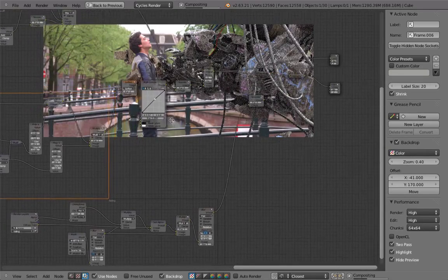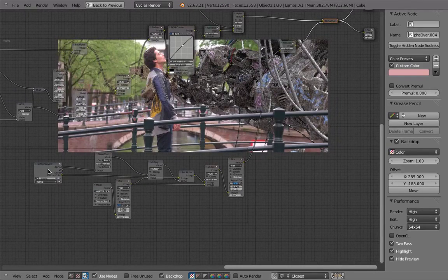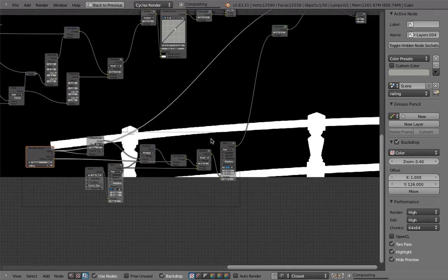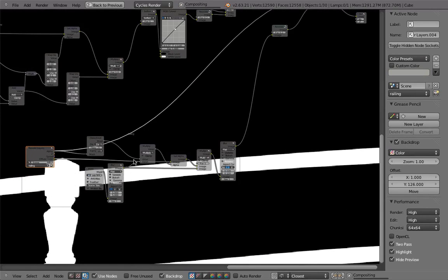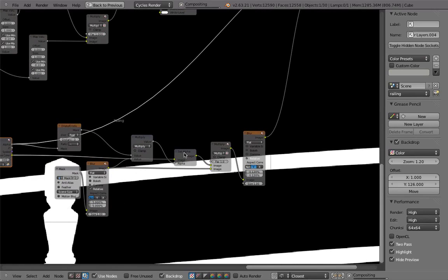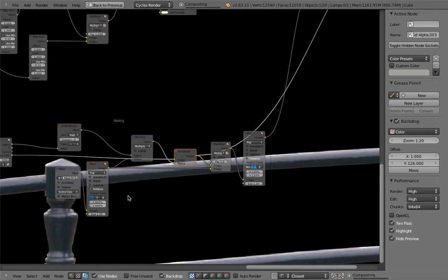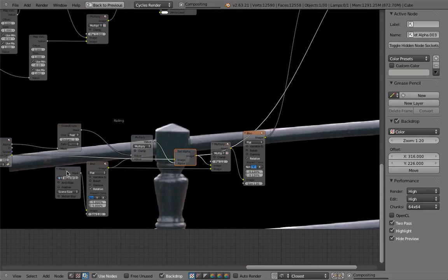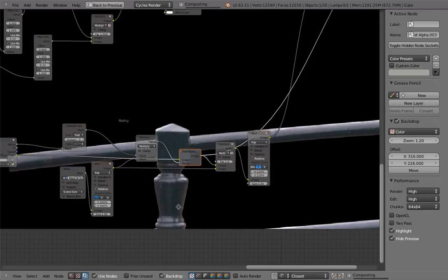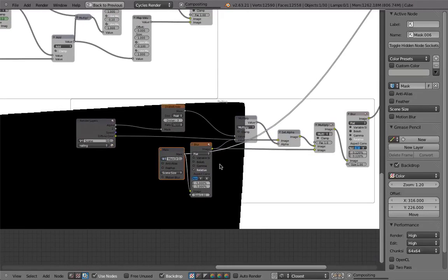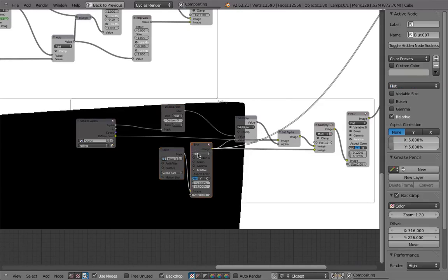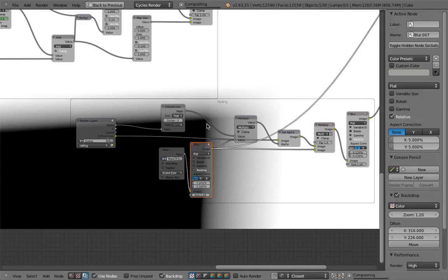Okay, so that's that. Then down here you have the railing. The railing is using the alpha channel to control the edge a little bit more. Then this edge is also put into the alpha channel. And here there is a mask. If I turn off 2-pass, I think it's better to see. So there is a mask which is being blurred, and I think this blur happened because this file was created before the feathering worked properly, I guess. Otherwise I would have used feathering.